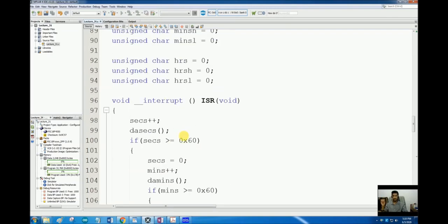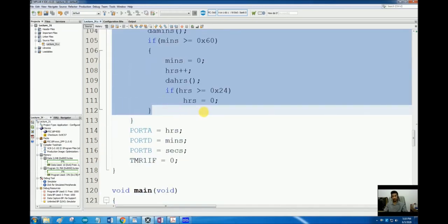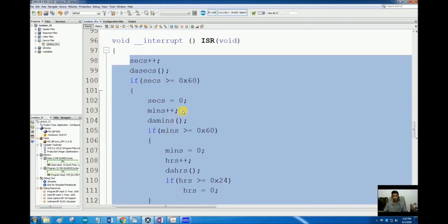So when the processor stops its current task and jumps to the ISR, inside the ISR we have many different conditions that we have to check. If we start checking these conditions and we stop the timer in the background, there are maybe 10, 20, 30, even 50 microseconds being consumed in this highlighted portion. So if we stop the timer, all these instructions, all this portion will become the error that will keep accumulating in our final time period.